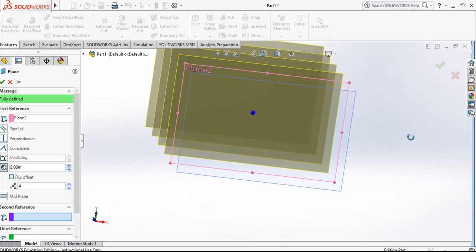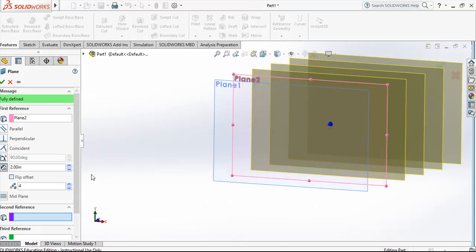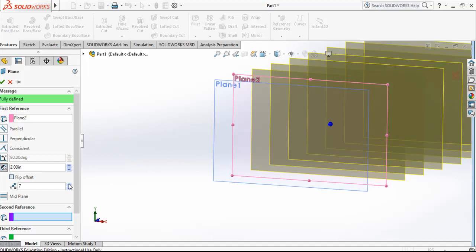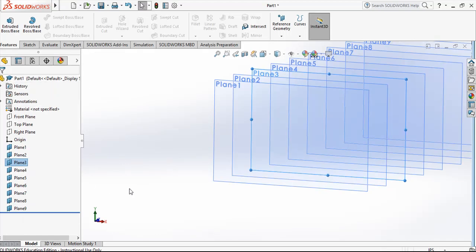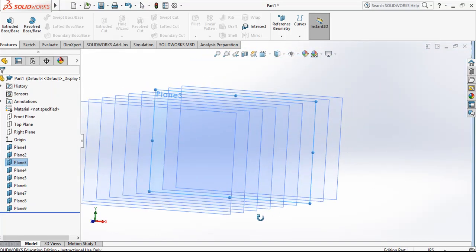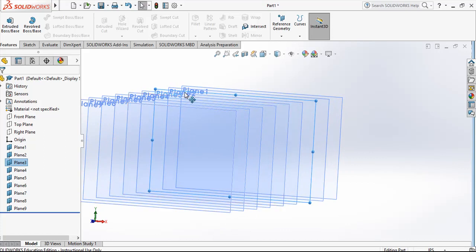As you can see here in the drawing, we can add as many as we want, and they will be spaced out the 2 inches that we wanted. So we could do that, and then we could come over here and see all the planes that it created. So when we go to draw on an object, we can draw on the first plane, and then on the second, third, fourth, and then we can connect them with a spline, also in some areas known as P-line.